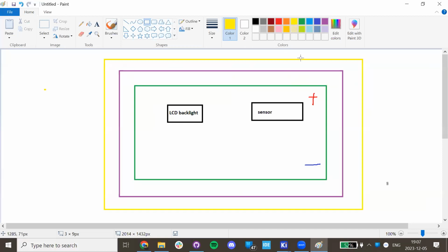So what we usually do is that the back layer we reserve for only ground. So the back layer is connected to the ground input of your PCB directly, and every single component that you place usually is grounded. If they need ground, which is very, very common, what you do is you just route out a trace and then you do a via. And now you have a direct connection to the ground plane. And as we are not routing any traces on the backside of the PCB, we have a very low impedance ground. So why is this important?